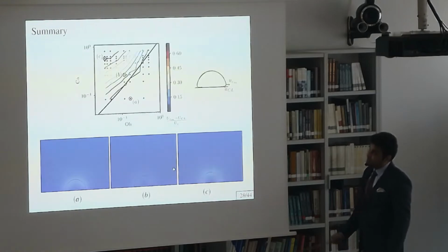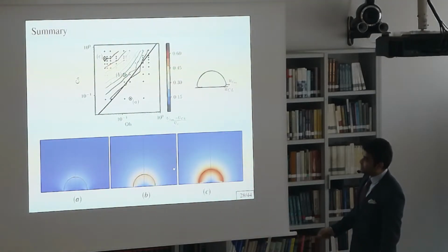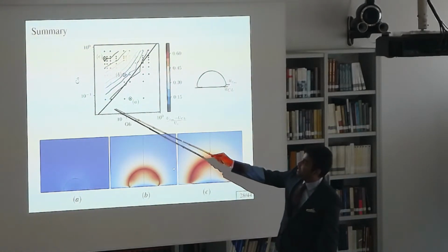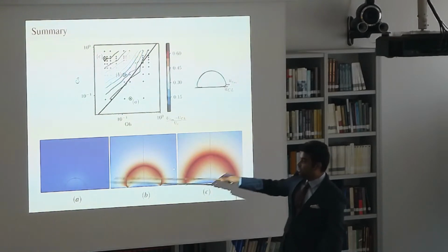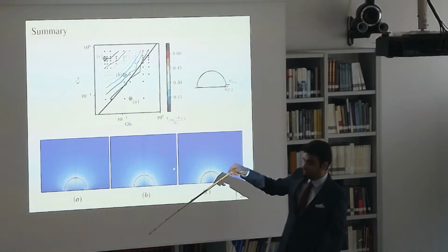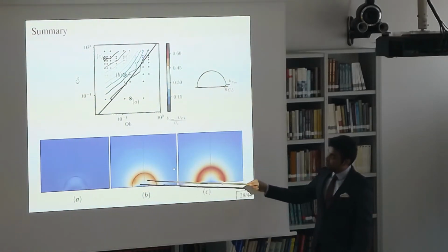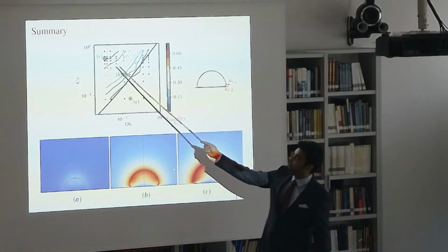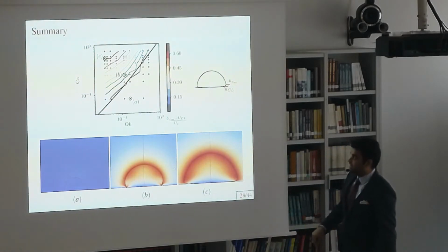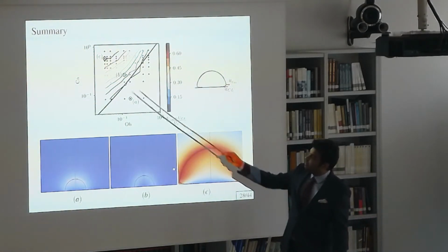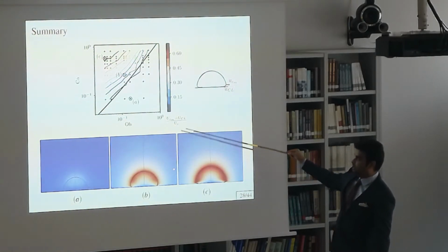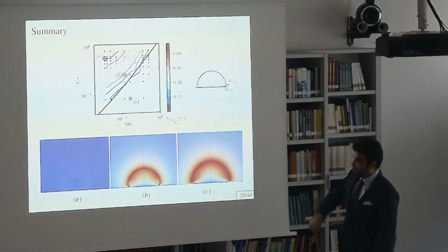And one can summarize what we observed in the previous slide with this curve, where I show you Ohnesorge versus capillary number, and in this region the bubbles are stable, they never grow. In the region where the capillary number is close to the critical capillary number, there is no microlayer, and if one wants to form a microlayer, we need to be in a regime where the capillary number is much larger than the critical capillary number. And the color map here is the difference of the velocity of the width and the contact line velocity as compared to the Rayleigh-Plesset velocity.